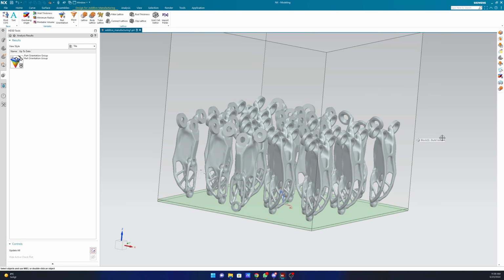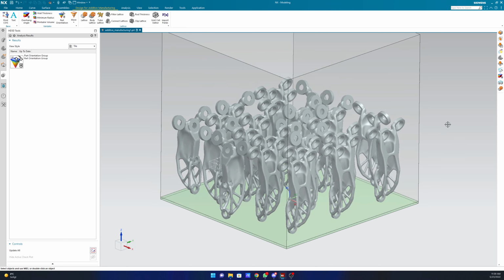So along the length will be better in some cases, depending upon the load and the characteristics we want. So you can say that we need to know the characteristics that are required, like will the part be in compression. So depending on that, the orientation can matter. But for now we don't know what this part will be used for. So we are just going with minimization of printing time and that sort of things. We're not talking about part quality now. Part quality depends on what application it will be facing. If we have that, we can make changes here.